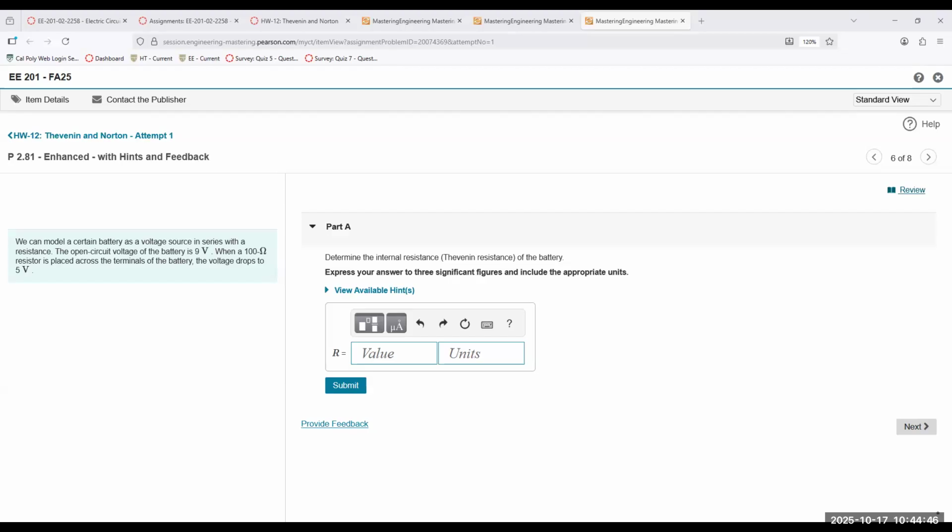Okay. So again, Norton proposed his own theorem that came to be named after him. So it's now known as the Norton equivalent circuit. Basically the same principle, saying you have a large linear circuit comprising voltage sources and current sources and a lot of other things. You could represent it all with one single current source named Norton current, IN. And the same Req for all the resistors in the network would be the Norton resistance or the Thevenin resistance, RN or RTH. And that's what it is, Thevenin and Norton. Very important concept in circuit analysis.